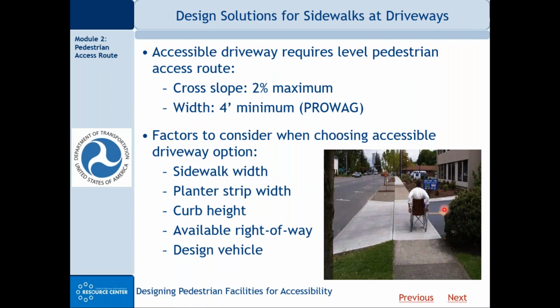Notice it looks like this driveway, from the arrow here on the pavement, is one way in. And so in that case, I think this driveway looks okay. But imagine this was a two-way driveway. Drivers could exit here and also enter here. Would you agree with me, for an exiting driver, this large shrub makes it difficult for them to see an approaching pedestrian? So if this was a two-way driveway, my advice would be to get rid of that shrub to make sure we have good sight lines so drivers can see pedestrians and pedestrians can see approaching vehicles.